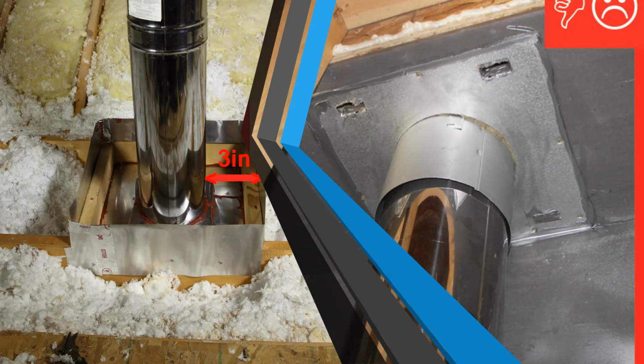And then of course maintaining clearance with insulation around it for not to come in contact with the flue pipe. They show a 3-inch clearance around there. I think the minimum is just 1 inch for combustibles, but they made sure they blocked around it. In this picture, it's vertical according to the horizontal of the ceiling rafters, and they basically boxed it around, air sealed that box entirely, air sealed around the flue pipe. And that's how you air seal it.